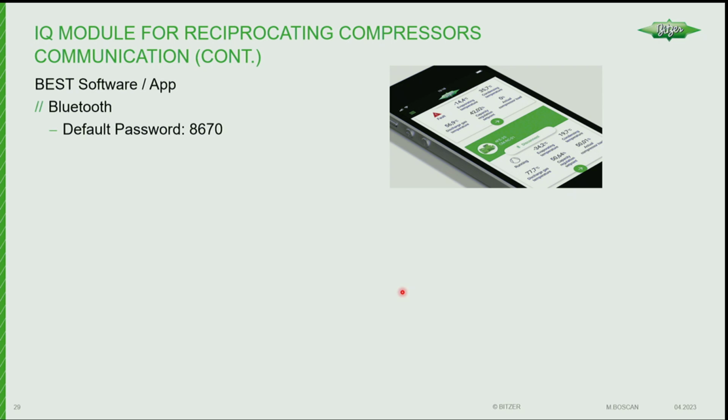So my recommendation is if you use the phone, if you happen to be at the store addressing something else and you just want to quickly take a look, you don't see any alarms on the controller or anything like that, you can tie in, look at it quickly, make sure everything's good. If there is an alarm on the rack controller, you can tie in real quick and see what it is, and maybe it's something you can reset from your phone because you know it's associated to the reason you were called in to begin with, and you can reset it from your phone and be done. But if you have to do any real diagnosis or real changing of parameters or interpretation of graphs, it's kind of small to do it on this.